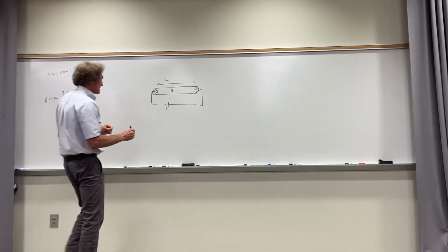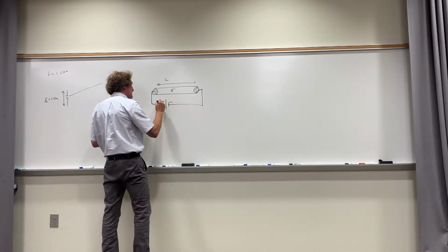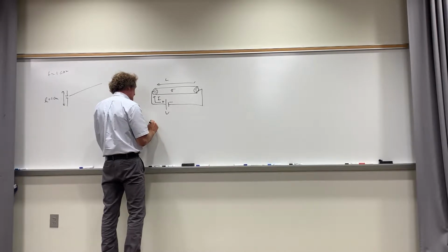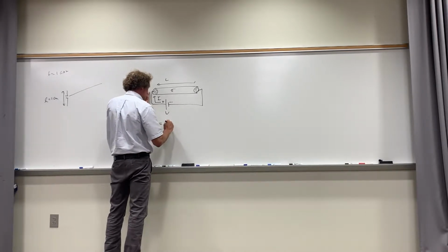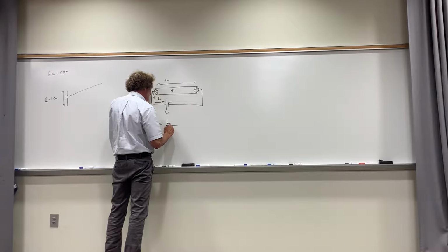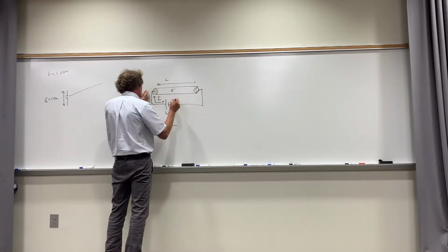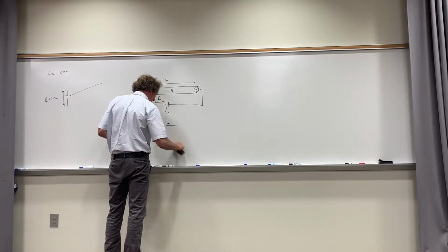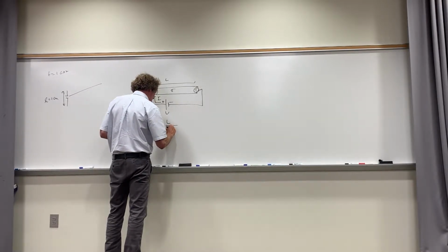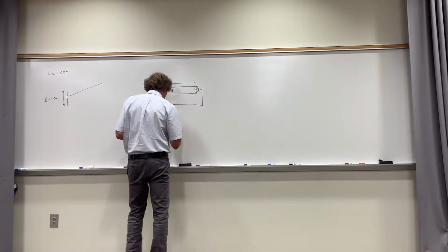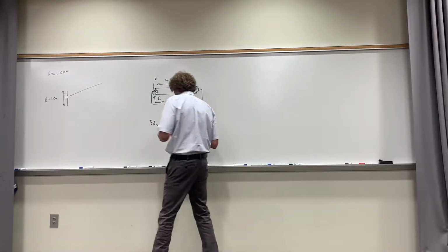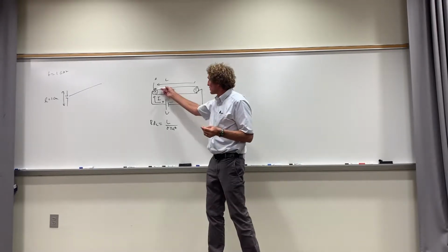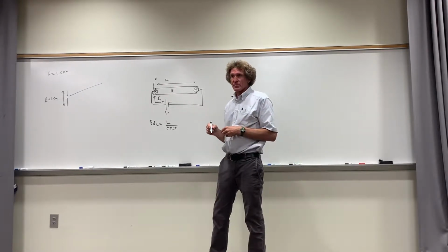Normally, the DC resistance, if this is plus or minus V, it would give a current, and R_DC would be given as the length over sigma times the cross-sectional area. If the wire had a radius A, it would be L divided by sigma, right? And then it would be pi A squared. This is called the DC resistance. It's as if the current would uniformly distribute over the actual cross-section. Do you remember doing this problem?